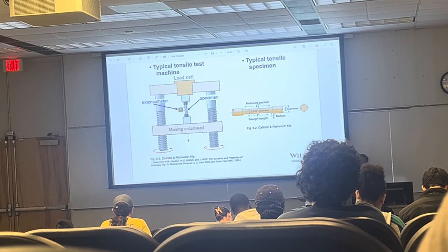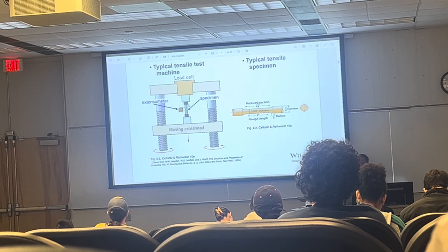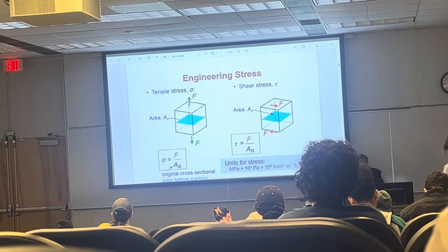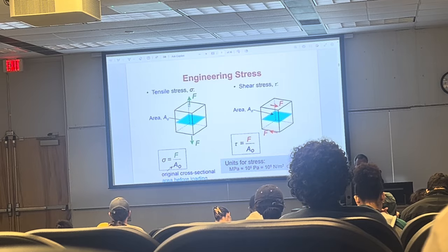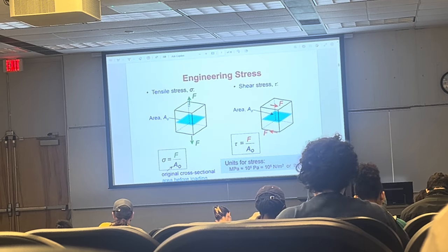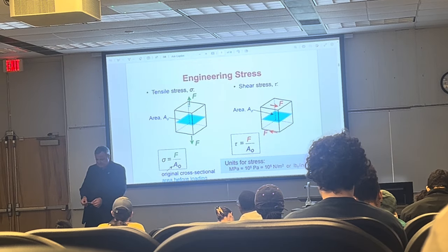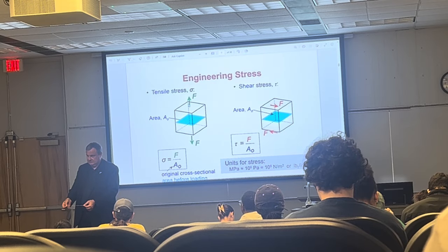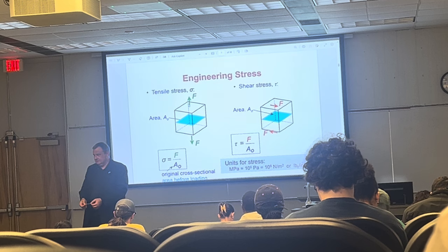Okay, so there's a machine that can do a tensile test. And another important thing is there is the Poisson's effect. If you look at this rubber piece, and I'm stretching it, what happens to the lateral dimensions of this rubber? It gets thinner, right? Less wide. That's called the Poisson's effect.